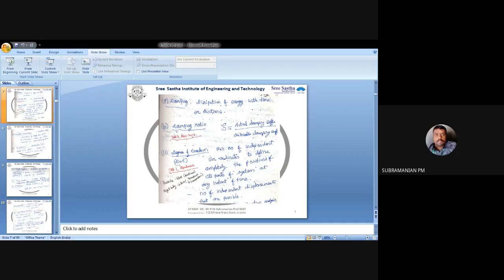And we discussed in the class a single degree of freedom system with a viscous damper, that is, having both spring and damper. What does damping mean? The resistance to the motion is given by fluid resistance, that is oil resistance. The resistance to the motion will be proportional to the velocity, that is the velocity of the piston, the dashpot piston.